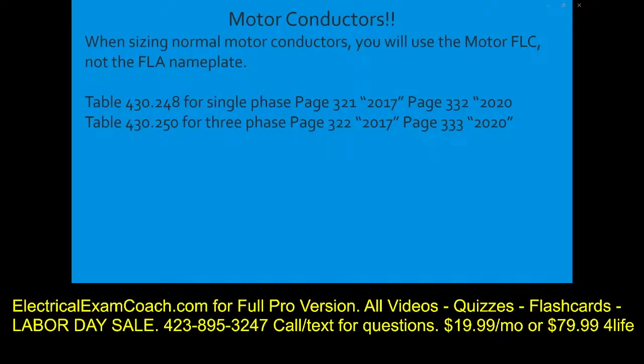Now let's learn about some more ground rules for motors. You're going to multiply the FLC by 125%. They consider motors continuous duty. Remember how we learned about continuous load and continuous duty previously? Well, it's the same thing. They're assuming that all motors are continuous duty, except, remember this is the National Electrical Code, when you're dealing with certain circumstances.